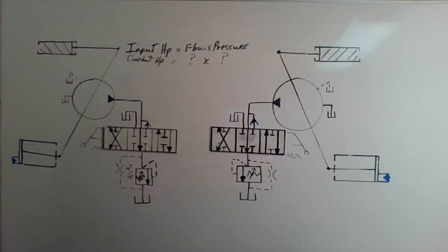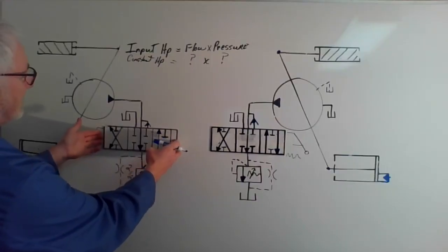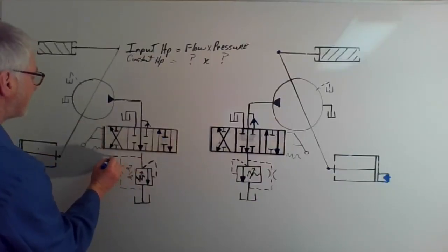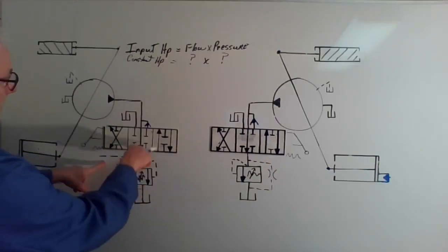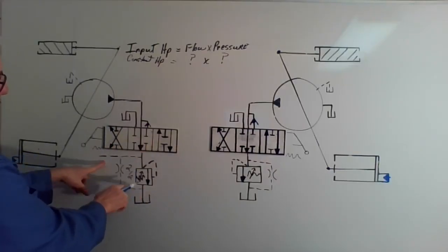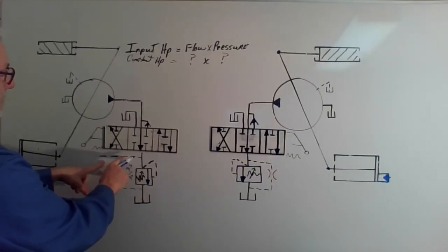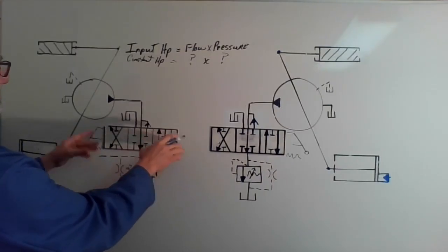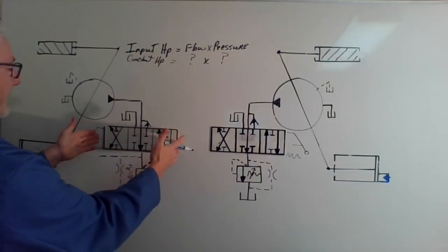Well, these are referred to as negative flow control valves, and the reality of it is, as soon as I move my DCV, if I was to put a pressure gauge here, I would see that there's 212 psi in order to overcome this normally closed valve. So that means there's pressure up here just sitting in neutral or neutral standby.